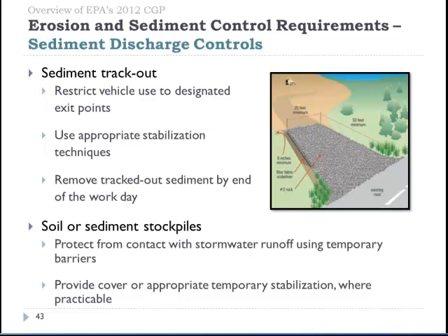In addition, there's requirements geared towards minimizing sediment discharge where soil stockpiles are used on the site. And here the requirements are geared at protecting those piles from contact with stormwater runoff, so creating some kind of barrier so that the runoff is either diverted or prevented from coming into contact, and to provide cover or appropriate temporary stabilization where practicable, so that direct rainfall onto those stockpiles isn't causing sediment runoff.